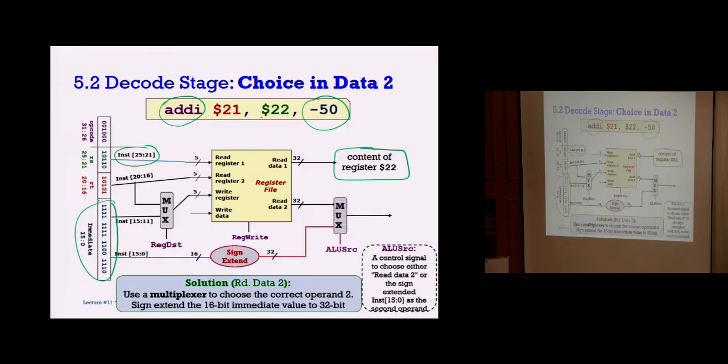So what do I need to do? I also need to do a sign extension of my data to become 32-bit. Now this one we covered in our tutorial 1. Why do we need sign extension? Because your ALU is already a 32-bit ALU, correct? So your immediate data you translate from 16-bit to 32-bit, so you can directly feed it to your hardware block. Now, when I extend this 16-bit and I send it over, I now must have another control signal with another multiplexer.